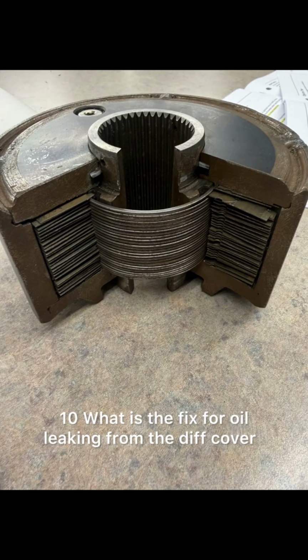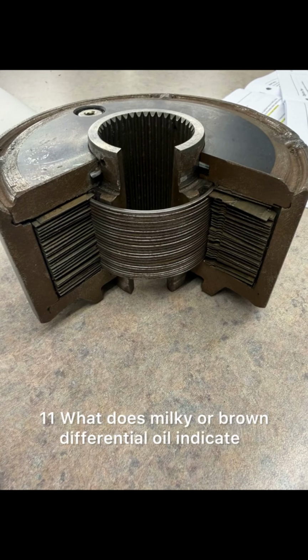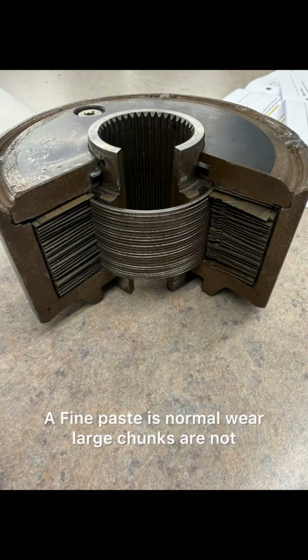10. What is the fix for oil leaking from the diff cover? A. Replace gasket or RTV and torque bolts to spec. 11. What does milky or brown differential oil indicate? A. Water contamination through breather or seals. 12. Are metal flakes on the magnetic drain plug normal? A. A fine paste is normal, where large chunks are not.